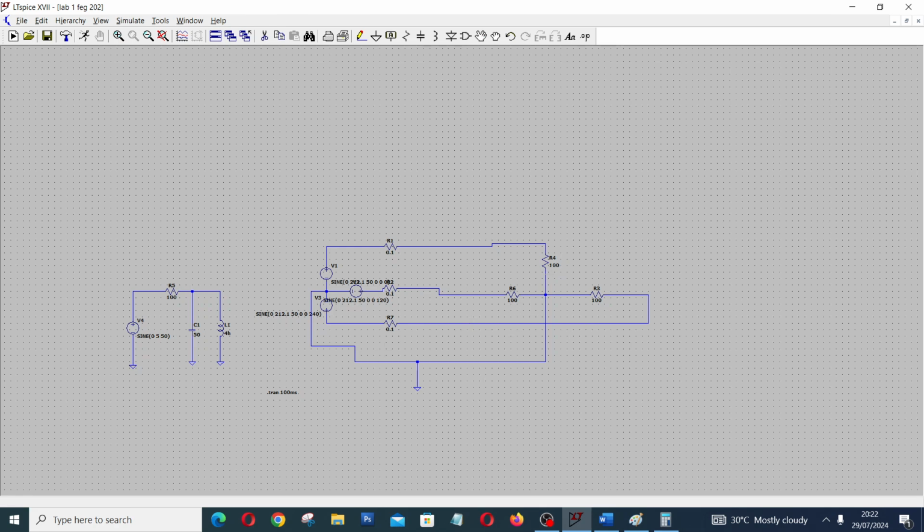When you look at it, as usual, the supply is star, but in this case, unlike the previous video, the load is equally starred. That is why you see that this is the star point, and the star point of the load is grounded together with the star point of the supply. That is one of the peculiarities of a star connected system. They are grounded together. Both of them have a common point, that is the neutral point. So it's a balanced load as usual. So we want to run this simulation.